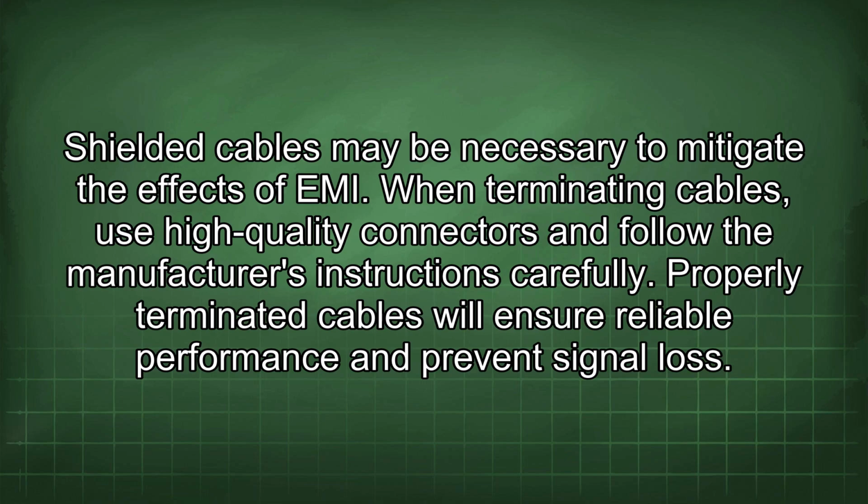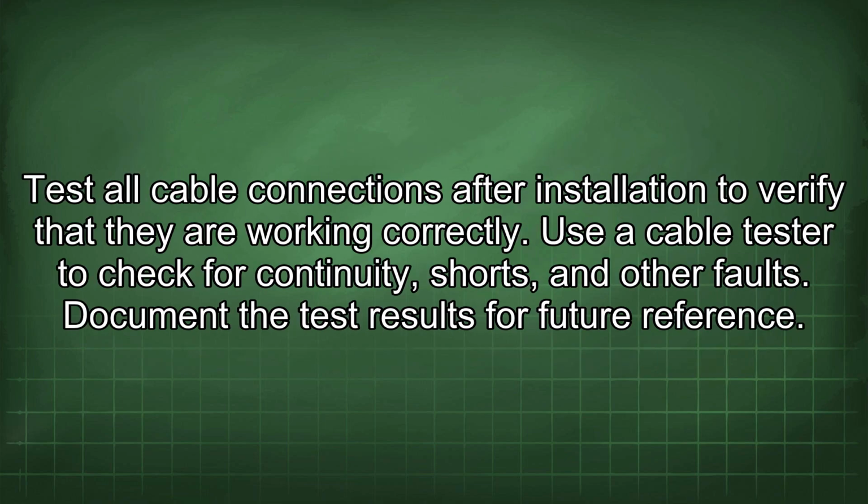When terminating cables, use high-quality connectors and follow the manufacturer's instructions carefully. Properly terminated cables will ensure reliable performance and prevent signal loss. Test all cable connections after installation to verify that they are working correctly. Use a cable tester to check for continuity, shorts, and other faults. Document the test results for future reference.